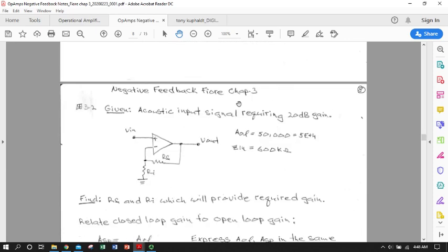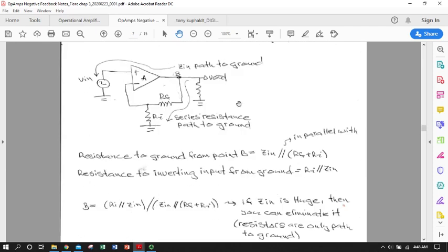Now, up in this expression, when we were deriving our beta in terms of these feedback resistors, we've kind of played fast and loose with this input impedance and defining the potential of point B with respect to ground, both straight through the resistors and over through the op amp. Well, that was kind of dicey. Exactly how did we use this Z in here?